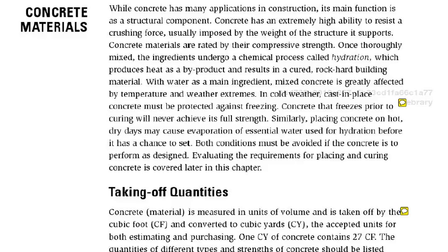You don't ever want to have concrete that freezes up on you. And again, I think the book says it will never achieve full strength, but over time, and I'm talking tens of years, you'll get the strength, but it's certainly going to slow curing down if it's frozen or if the temperature is low, and I'm talking below 50 degrees actually. The buildup of strength in concrete is a lot slower than if it's above 50 and say into about 90 degrees is optimal.